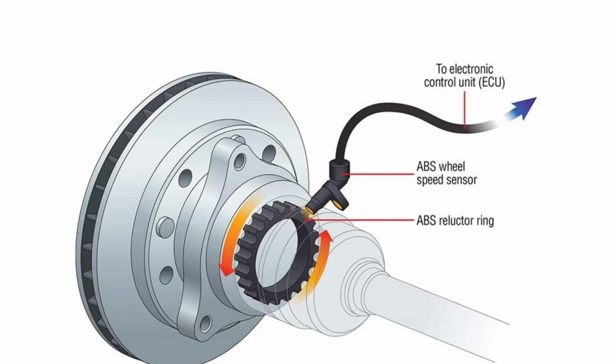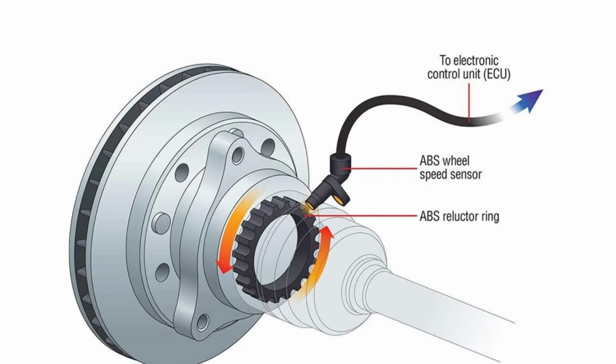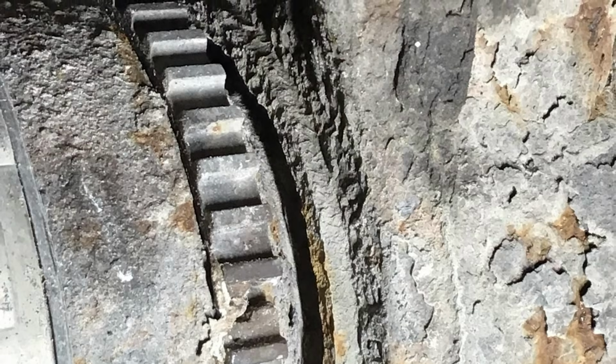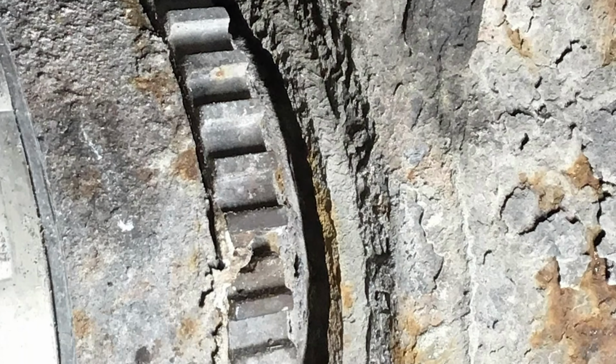Then the second common culprit is a failing ABS sensor in one of the wheels. It may send wrong speed data, and so the transmission goes to limp mode to protect itself from potential wheel spinning. A good scanner will help you understand which wheel sends wrong data. It may be a faulty sensor, but in older cars with high mileage, I would also have a look at the ABS rings. They may be rusty and destroyed, which will affect ABS readings.